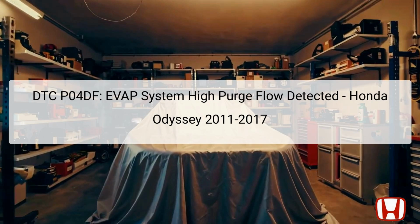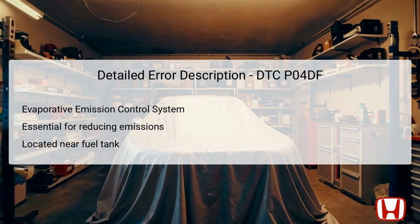Inappropriate flow detection, as indicated by DTC P04DF, can lead to increased emissions and potentially affect fuel efficiency. Proper diagnosis and repair of this issue are essential for both vehicle performance and environmental compliance. The P04DF code signifies an issue within the evaporative emission control system, EVAP, of the Honda Odyssey. This system is essential for capturing and storing fuel vapors from the fuel tank to minimize emissions during engine operation.